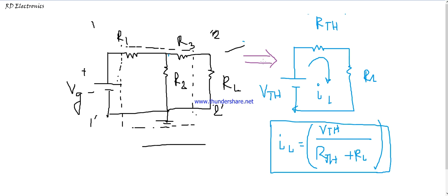So that's why we need the Thevenin equivalent circuit or Thevenin equivalent network, and that's why Thevenin introduced the new concept. How can we convert this complex circuit to a simple circuit to measure the load current? Because this circuit is very complex. Using mesh analysis, without Thevenin theorem, we can analyze the circuit, but here two currents flow, I1 and I2.